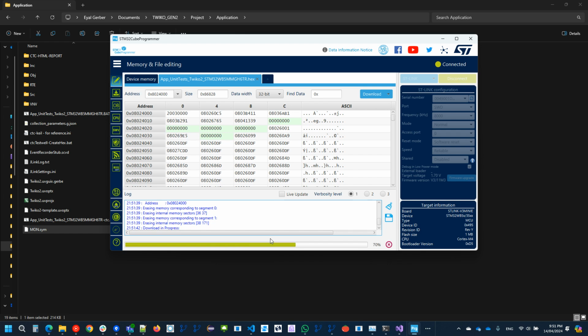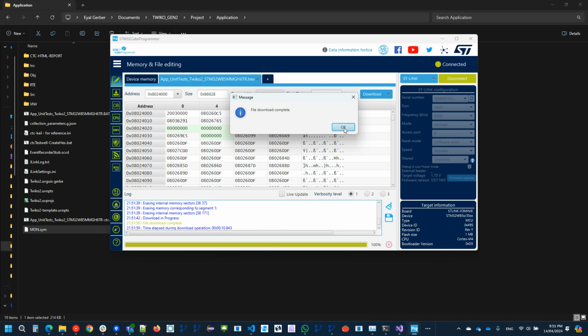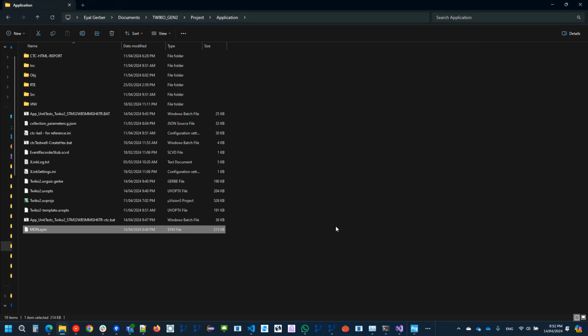You also want to make sure that no other serial data will be printed from the microcontroller. It will just generate noise for you and perhaps for the tool that will later analyze the serial data. It will save you the effort of trying to take the coverage data and the other typical serial data and separate them. So just don't put anything else except for the coverage data. I already took care of that in my code. Disconnect.